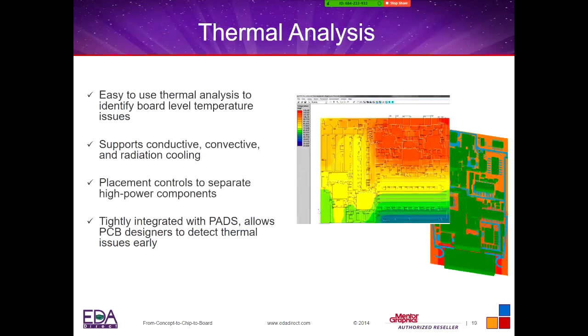As long as you're putting in the properties for the temperature range, we can come in and check to make sure where our hot spots are on the board. We can find out if we need to put in heat sinks, maybe some mounting holes to cool that area. So you've got a nice little thermal analysis tool as well.